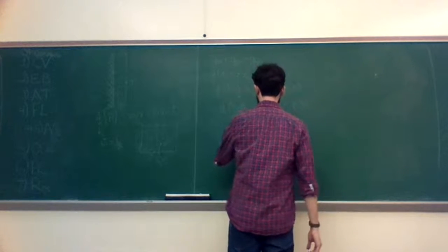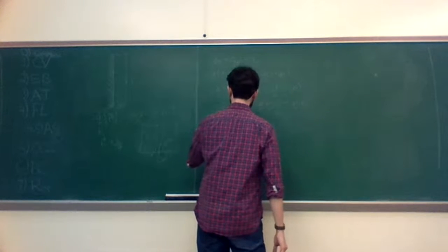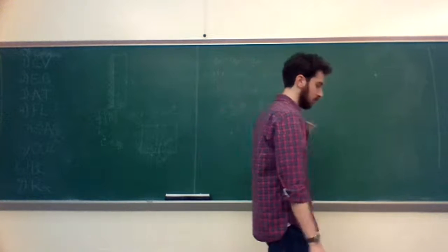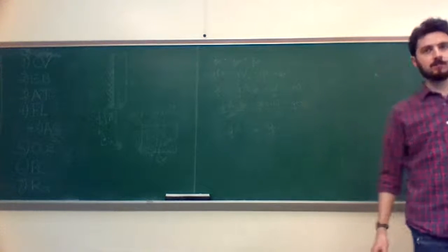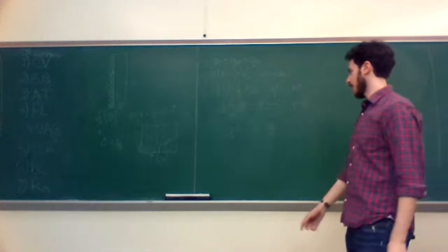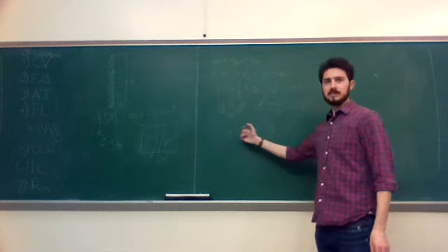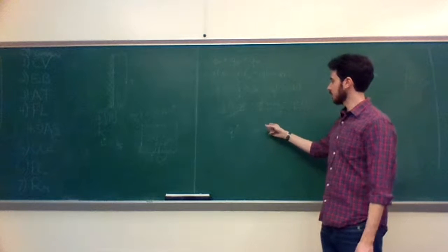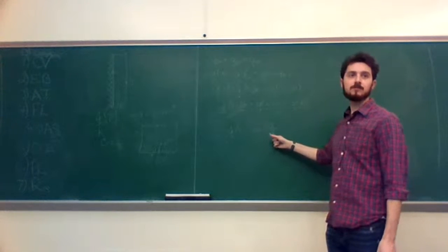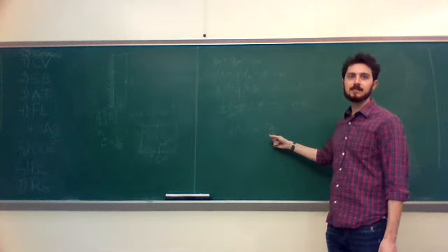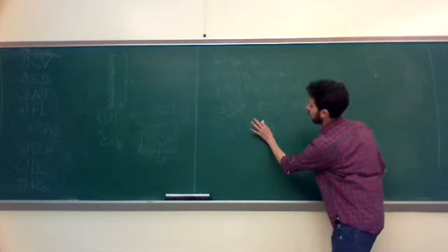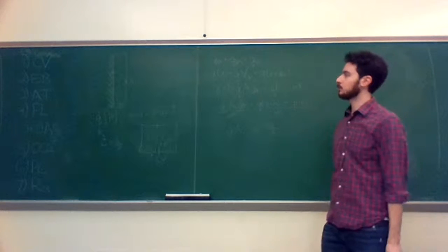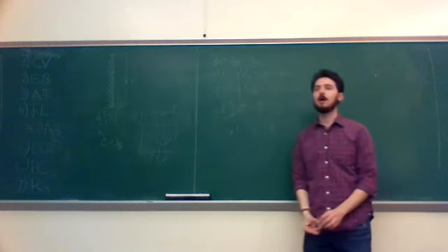And now the left side is Q dot A, so watts per meter cubed times an area, which is meters squared. So you've got something in terms of essentially watts per meter on the left side. And then this is watts, but differentiated with respect to x, so this is also essentially just watts per meter. Feel good so far? Okay. What's our next step?